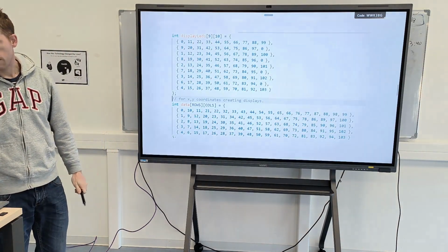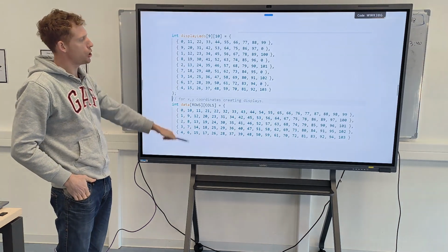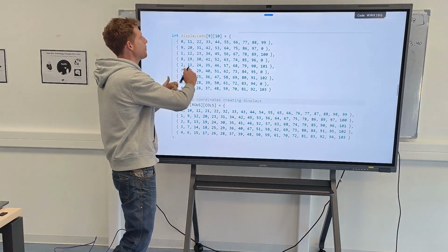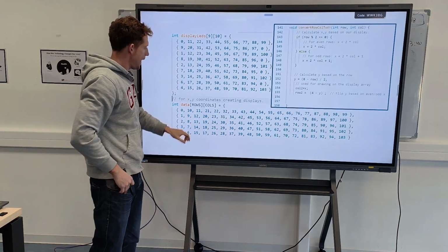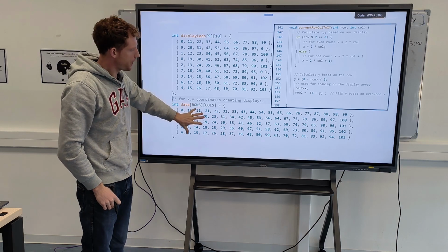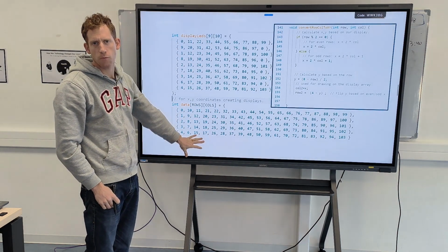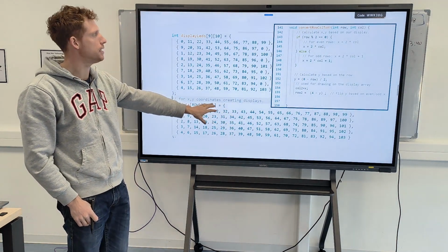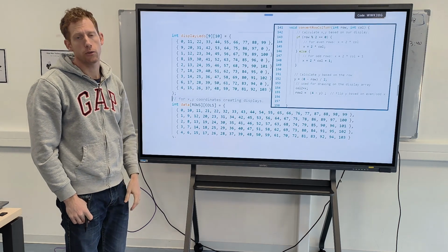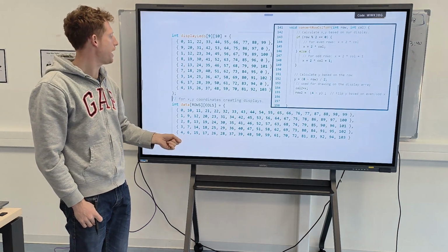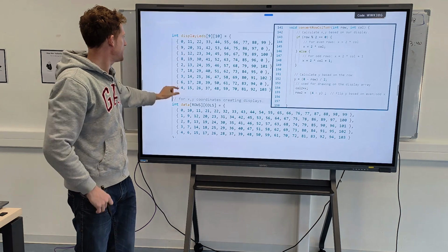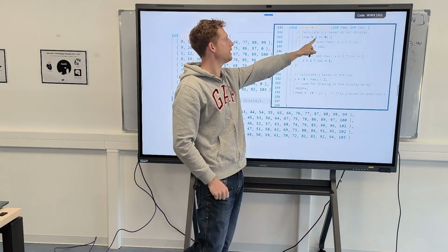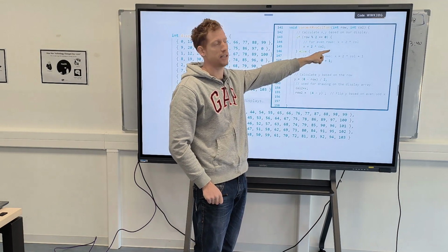So basically the problem I had was I had 2 arrays. One was my button array, and it was different dimensions. And this was my display, and I wanted my buttons to match my display, so when I press on a button, it's going to light up that LED. And so I was able to think about it and figure it out. All you have to do is split this into that mathematical zigzag pattern, just mod the row, and check it to see if it's 0.